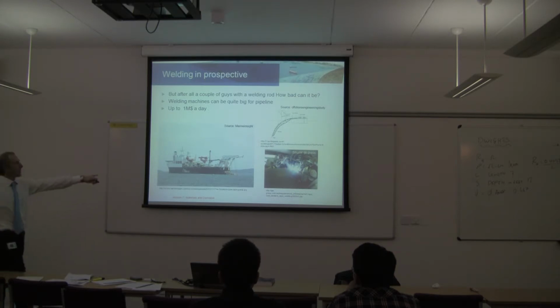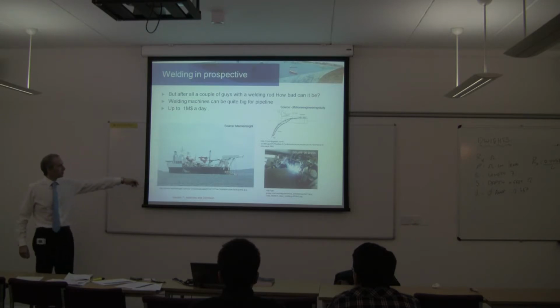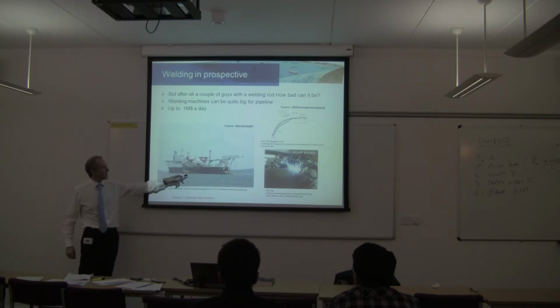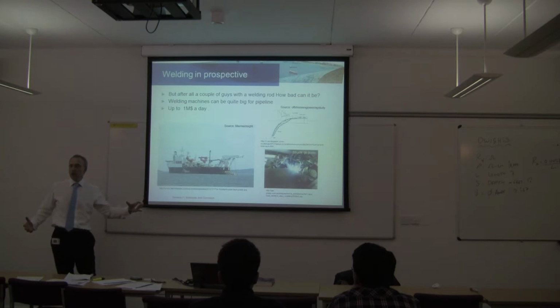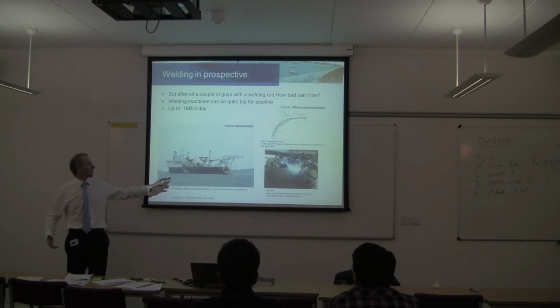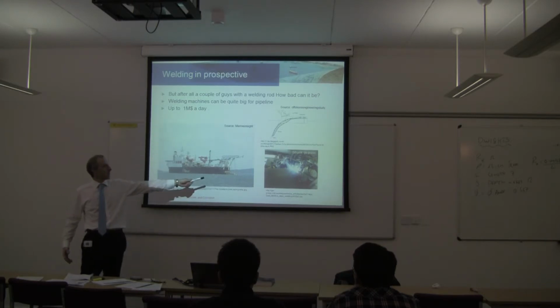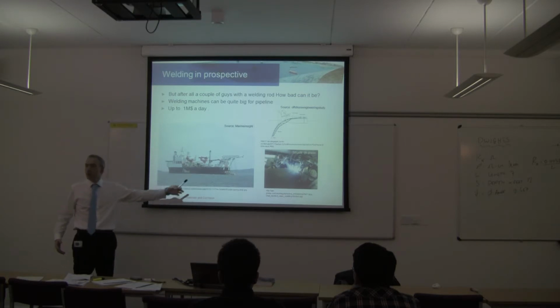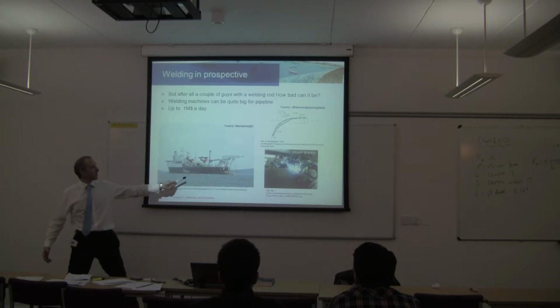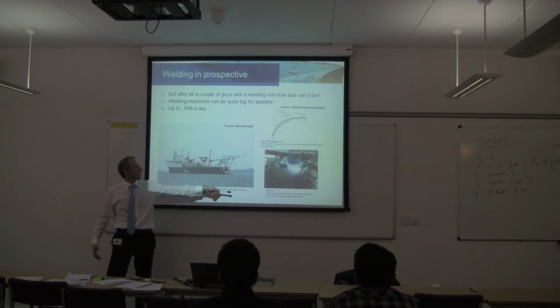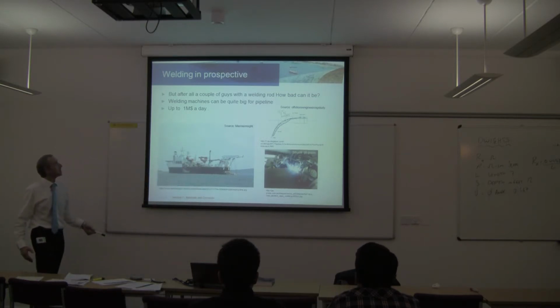Okay, this photo on the left-hand side is a lay barge. Inside here is just like one big factory where the lengths of pipe, or joints of pipe, as we call them, are brought out to the lay barge and loaded on. Down inside the hull is a welding line using equipment like you see there in the photograph, and then the pipeline comes off the back into the sea, what they call a stinger.